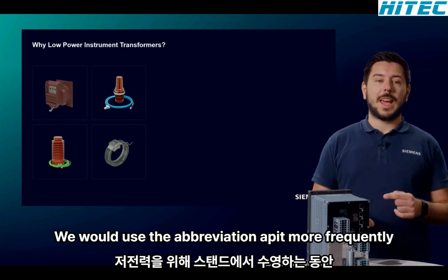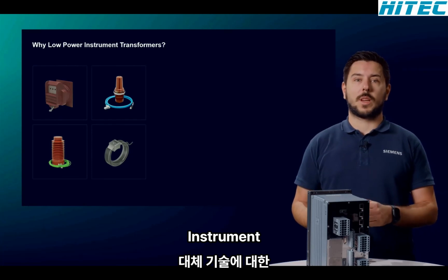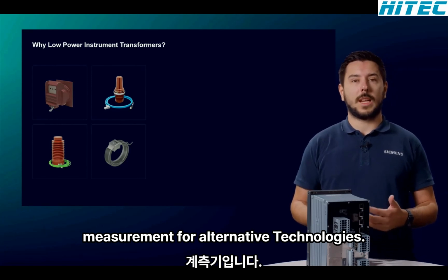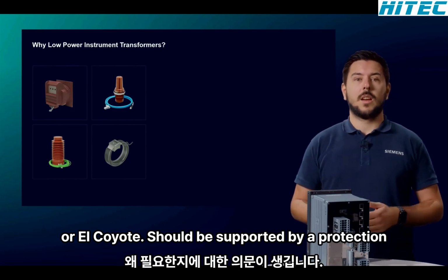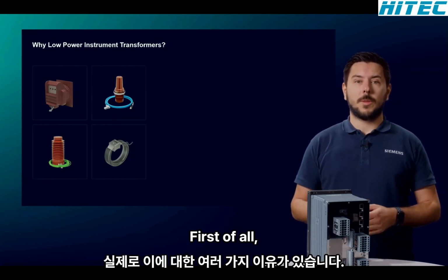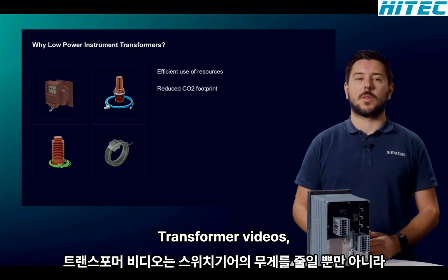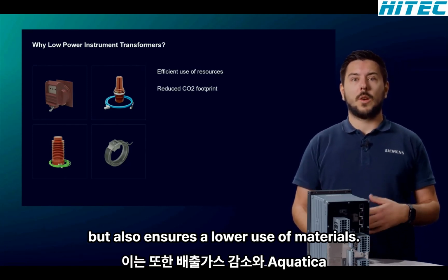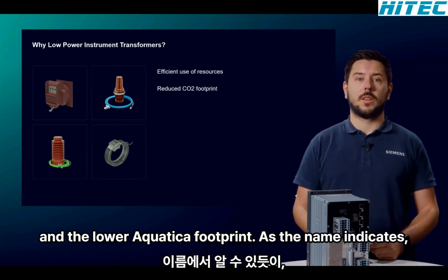We will use the abbreviation LPIT more frequently during this webinar. This stands for Low Power Instrument Transformers. These are sensors that enable current and voltage measurement through alternative technologies. Now the question certainly arises as to why these sensors, or LPITs, should be supported by protection devices. There are actually a number of reasons for this. First of all, there is the small size and weight of the sensors compared to conventional current and voltage transformers. The use not only reduces the weight of the switchgear, but also ensures a lower use of materials and thus also lower emissions and a lower ecological footprint.